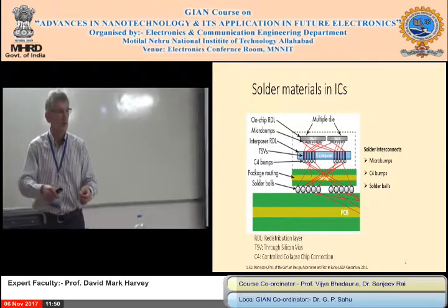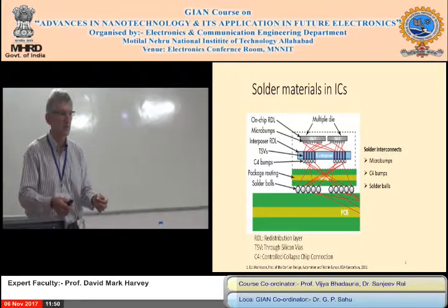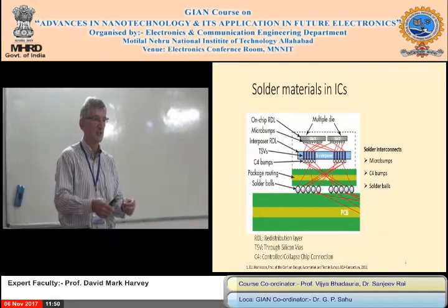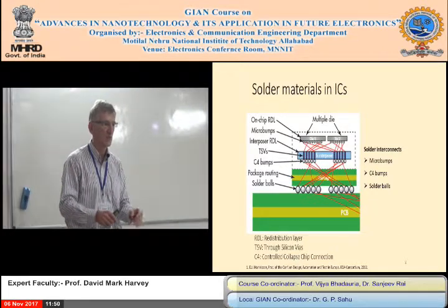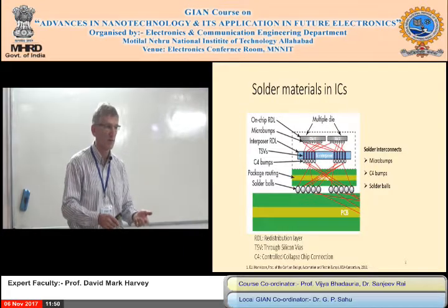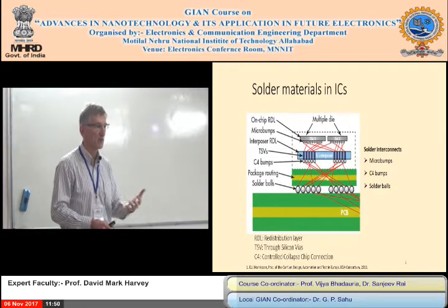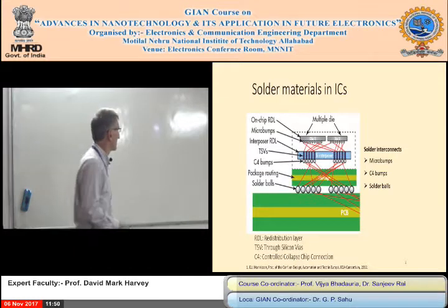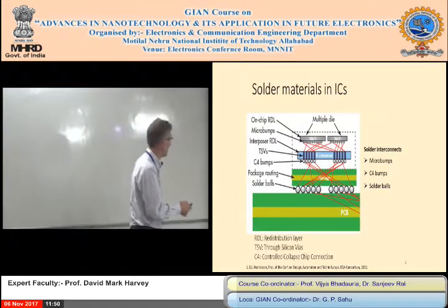Now, we've all done soldering. Have you done soldering in your courses? Now, it used to be lead solder, now it's lead-free, which is slightly more brittle, so it's created more problems. For the environmental aspect, you don't want to use lead in products. So look at this chip over here.